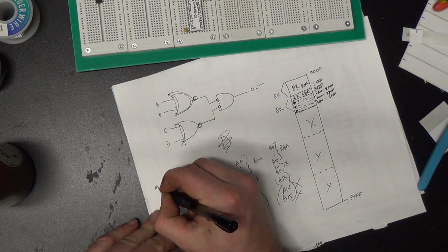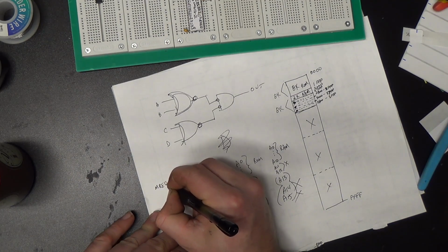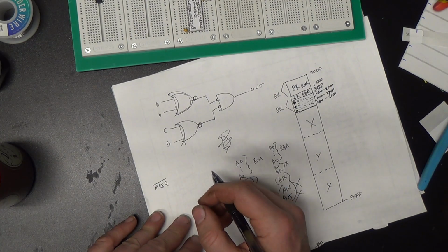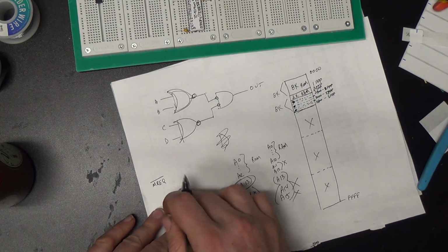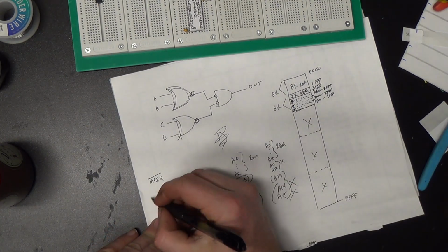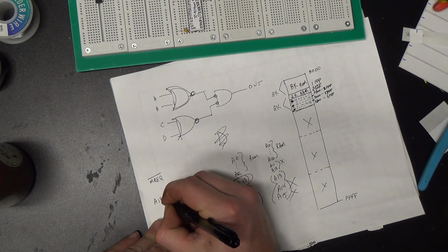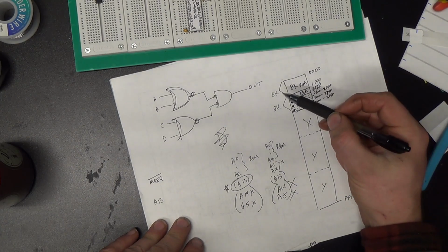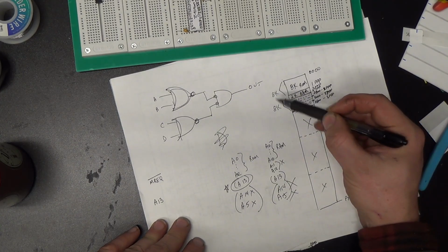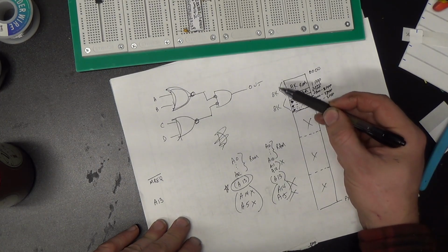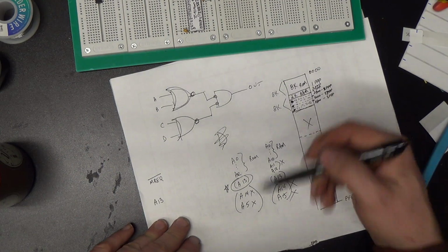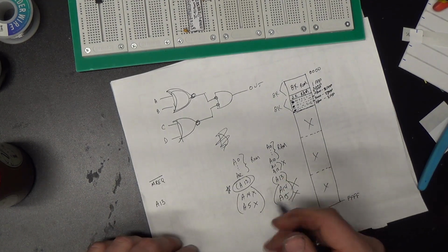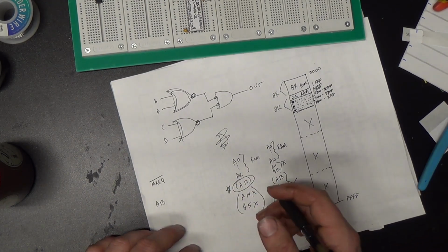So what we'll do is we'll take the memory request line, and remember it's active low. It goes low when there's a memory cycle in progress. And we'll take our A13 line, right? That's going to be selecting between which of these 8K segments we're looking at. A13, recalling our binary arithmetic, which I really can't do in my head, so I shouldn't be acting like I can.